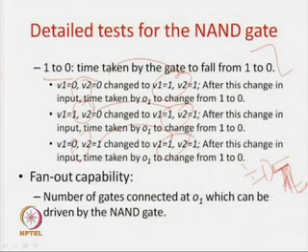Again you have to apply the 3 cases and find out the time delay taken for this fall, and then you can represent that the delay for the 1 to 0 fall is so much in the worst case, or so much in the average case. So, how many tests have we done till now? We have done 4 for the basic functionality, and now for the delay test we are applying another 6 kinds of inputs, so 10 inputs till now. So, this was about the functionality of the NAND gate in terms of logic as well as the delay.